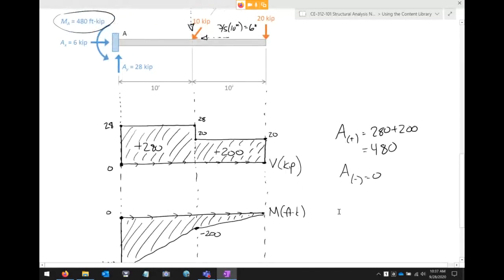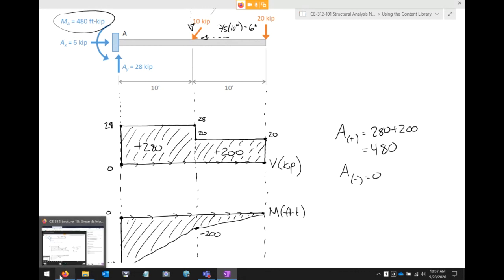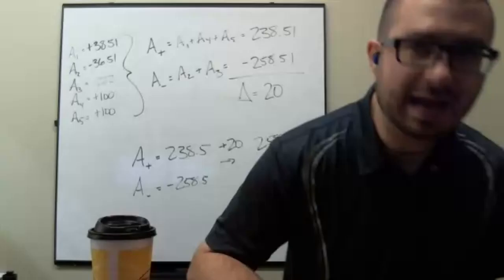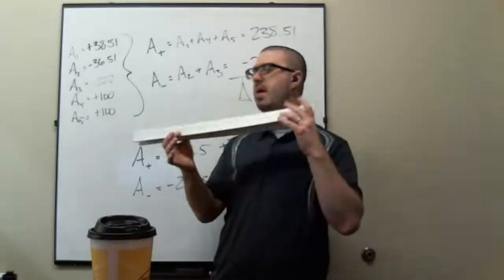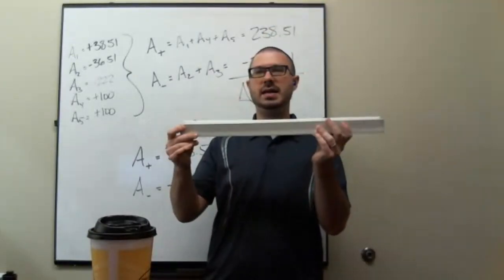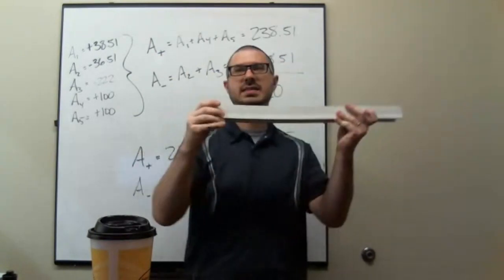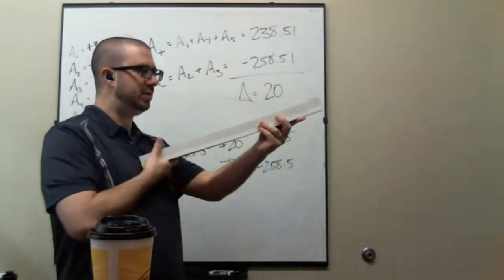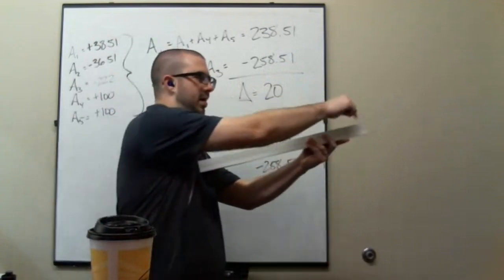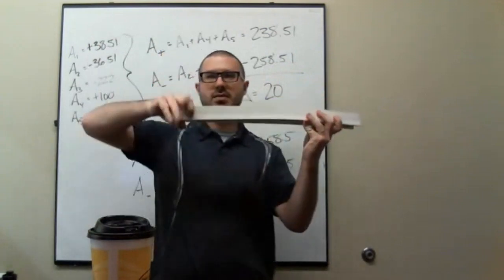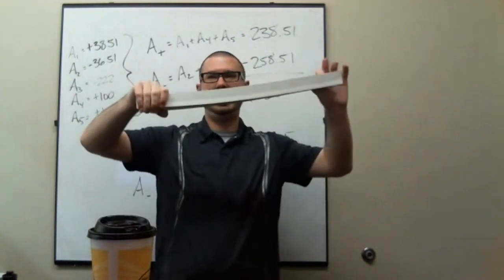One of the things that you'll see in the cantilever beam is that if you look at the moment diagram, all of the moments are negative. So this moment diagram is completely negative. What does that mean? Okay, well, let me show you something. I have here my mock beam set up, and let's say for the sake of discussion that this is the clamped end. Okay, so this is the fixed end, and there are some loads right here and right here. Now here's the clamped end, and imagine that there's loads here and here.